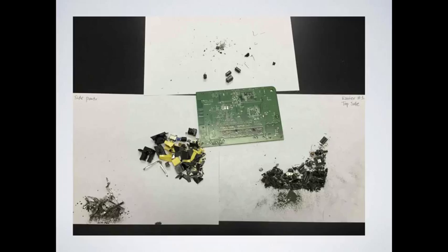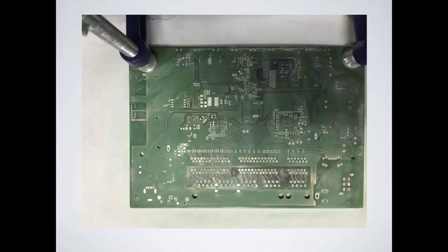So I was like, okay, let's get to work. Let's try this. I really like this particular combination. What I do is I take the very top and I use the sanding disc. The sanding disc comes in different types of grits. The ones I used on the black boards were the 120, which is kind of the middle of the road, and then the 240. Because I didn't know how thick this solder mask was going to be, and I didn't want to damage the copper, I was like, this is the first go around, so I'm going to take the 240.